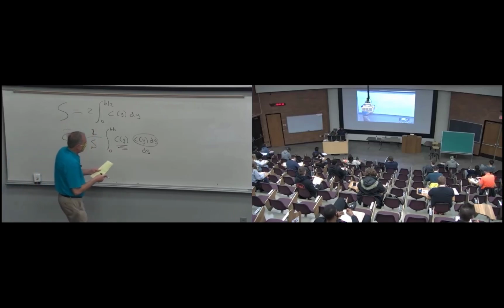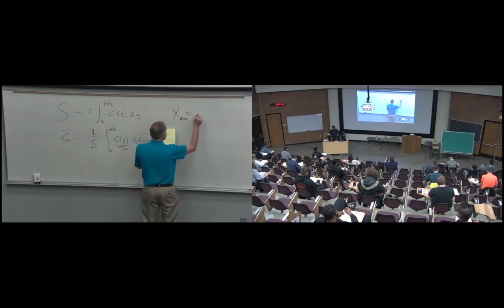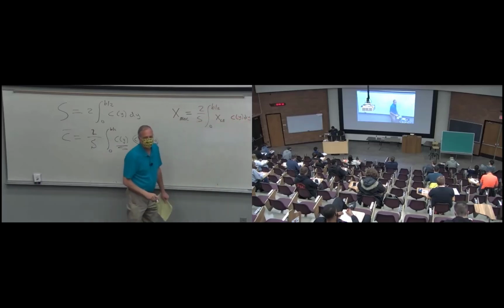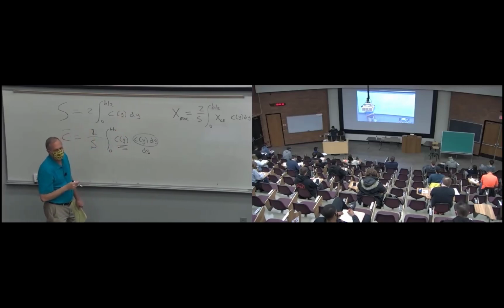All right, and so then the formula for the x distance, so this is the x distance back to that mean aerodynamic chord. It's the same kind of formula, except that now we average the x distance back to that leading edge, right? The leading edge is tapering down. This is just the distance x down to that, and we're going to figure out the average distance down, and that's going to tell us where that C bar is.